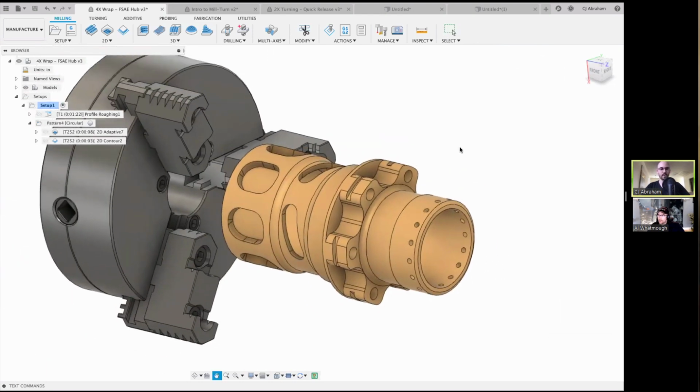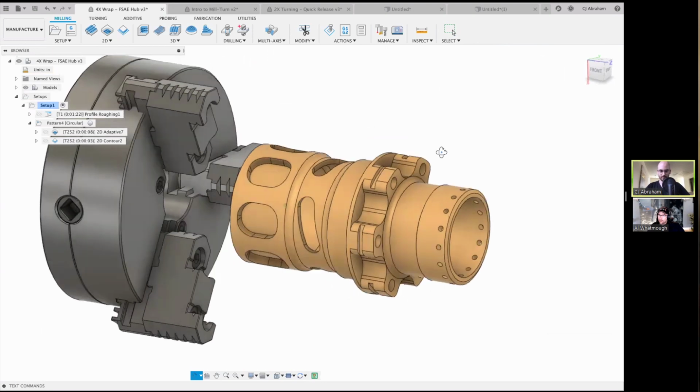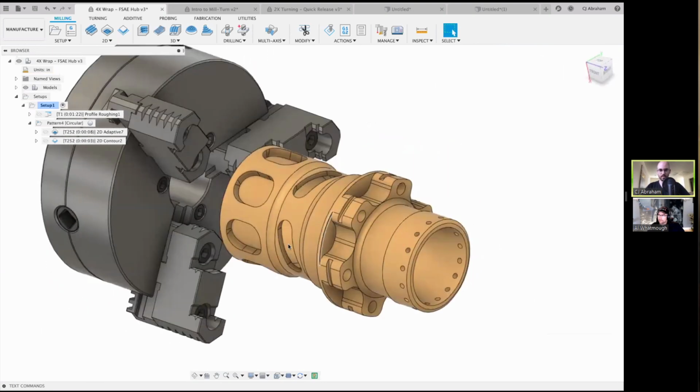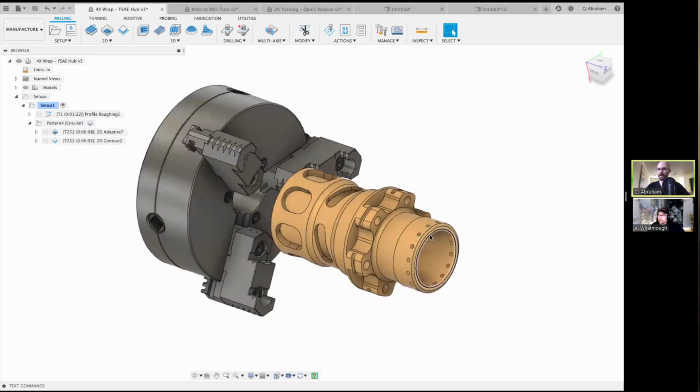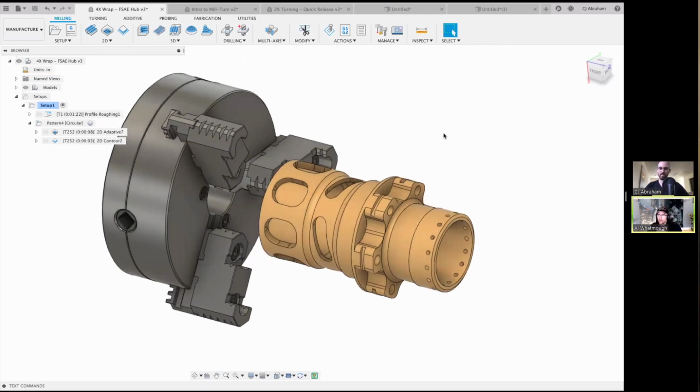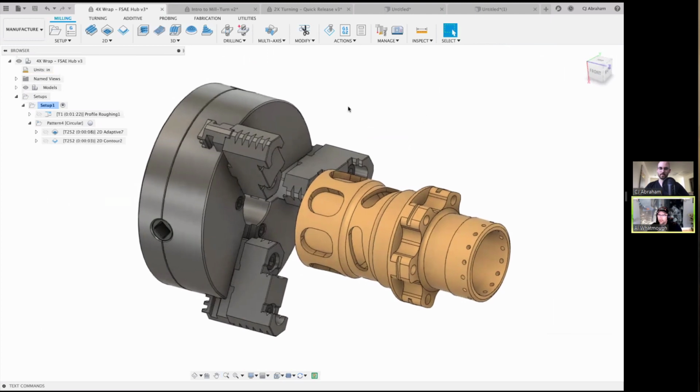So the next thing I want to do is an axial toolpath. I mean, a radial, sorry. And it looks like we could either do the pockets on the side here, or we could also do these drilled holes. Let's do the pockets on the side so you can explain, because with 2D there's a couple different radial fields and each of them matter.